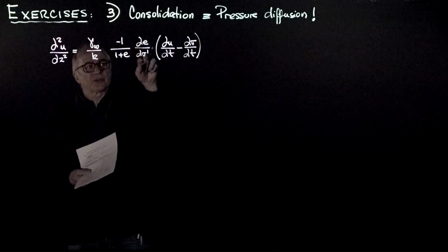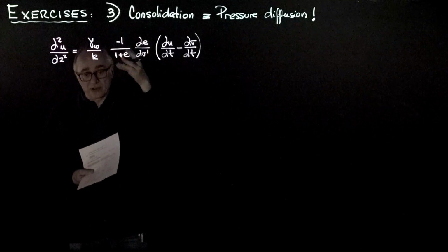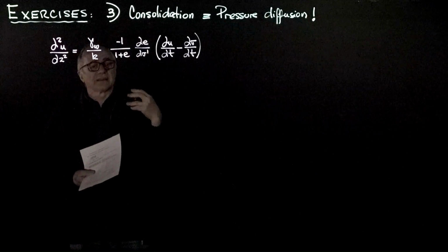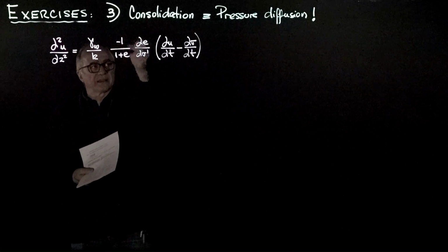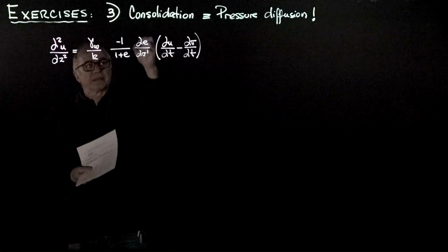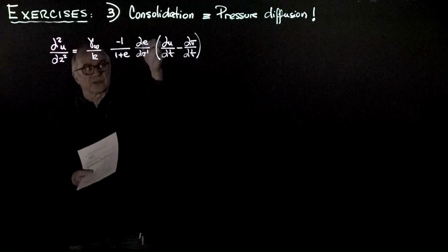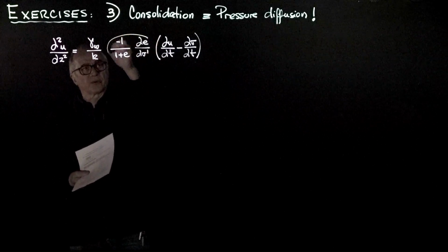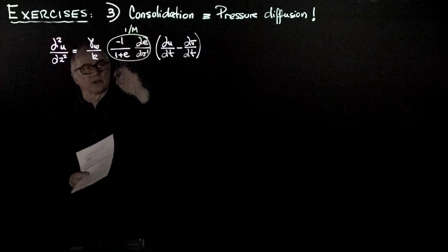And the ratio between the stress increment that caused the vertical strain to the value of the strain is the constraint modulus. The reason why there is a negative sign here, and allows me to flip this parenthesis, is because the void ratio decreases as the effective stress increases. So this is what we call the inverse of the constraint modulus.